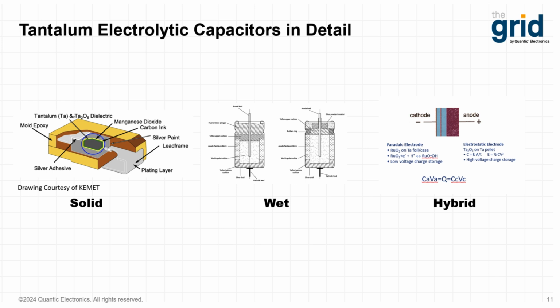In addition, they offer very low ESR, which allows for larger currents to pass through the capacitor with less heat being generated in the process. So, tantalum capacitors are available in voltage ranges from 2 volts to 500 volts, but common ratings fall more in line with a 2.5 to 50 volt range. Common capacitance ratings for tantalum capacitors range from 1 nanofarad to 72 millifarads.